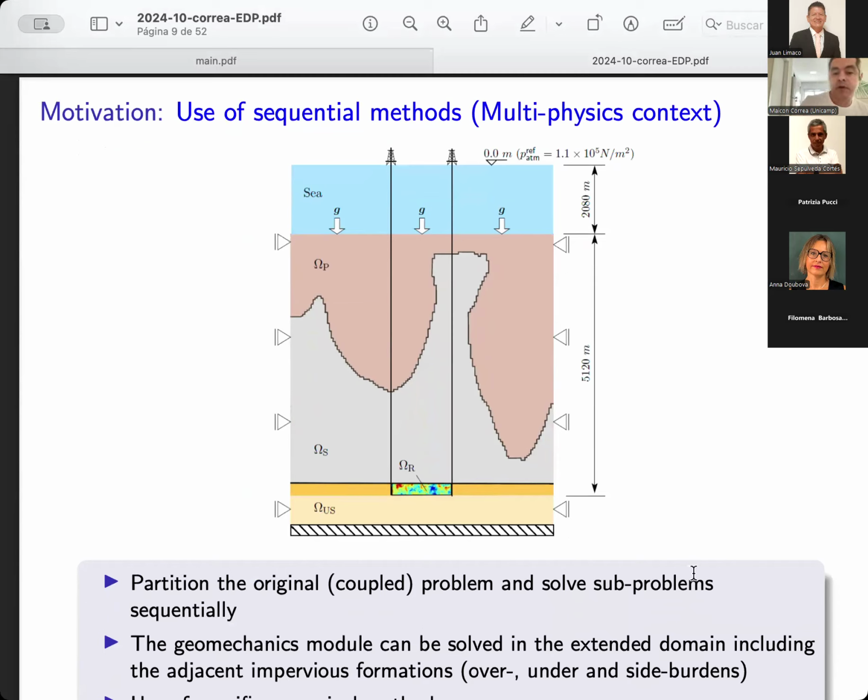Okay, so you have three phases, but the component gas may be present in the oil phase and also in the gas phase. And again, another really important simplification here is we assume all the pressures are the same. So we don't have capillary effects here. We are not accounting for the capillary effects. Okay, going forward. These are the mass balance equations for the three components.